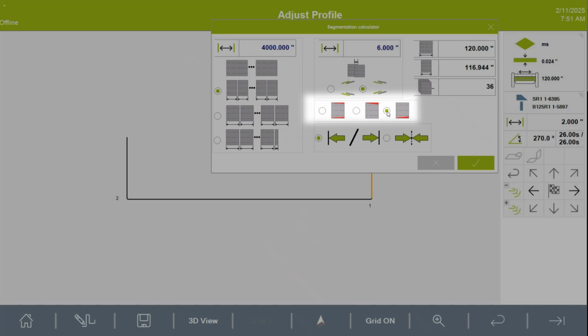Usually parts that have a nailing strip, for example, a drip edge or whatever, if your bend sequence is that you're bending that nailing strip last, then this is the option you want to use, because we don't care if that nailing strip absorbs all this disparity. It's going to get screws put in it and covered up anyway. So these are the three choices that you have for selecting where the disparity in the material goes.